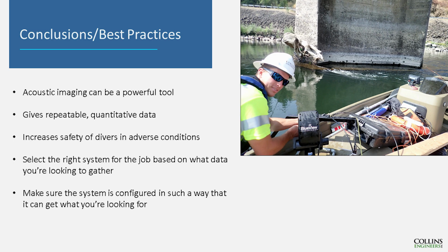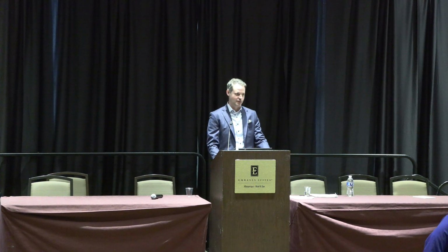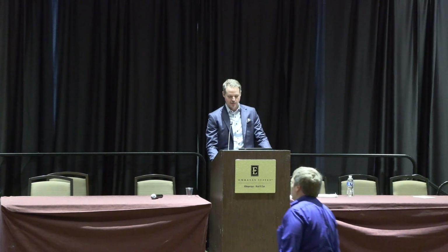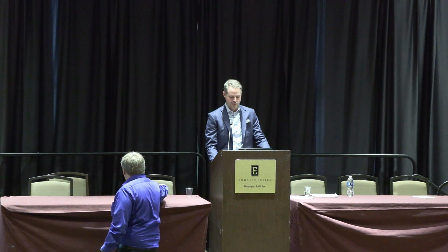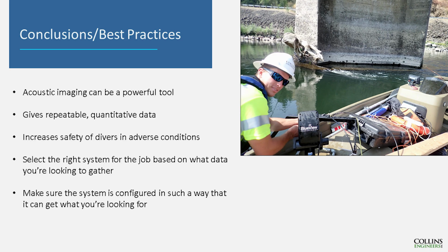So acoustic imaging can be a powerful tool, but it's still best used in conjunction with divers because it can't see past obstructions, like I said, can't tell you the type of material that you're looking at, or discern really small scale defects like small areas of voiding at the interface with the channel bottom. It gives repeatable and quantitative data if you understand the capabilities and limitations of the machine that you're using. It increases safety by being able to determine potential hazards before a diver even enters the water, like that timber debris.